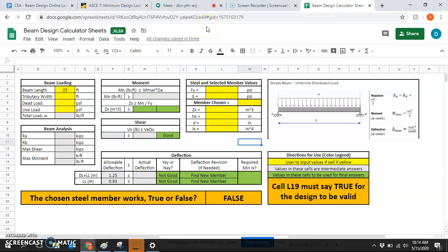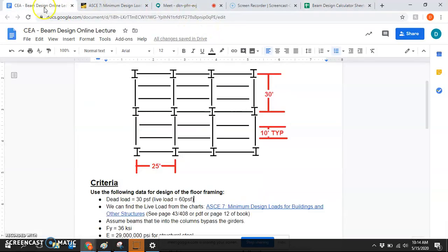And this is what varies between interior and exterior beams. So an interior beam is going to be responsible for halfway to the nearest beams. So this beam right here, where my cursor is, is responsible for halfway to this beam, all the way through halfway to this beam. And that width is going to be how many feet? 10, because it's 5 in one direction, 5 in the other.